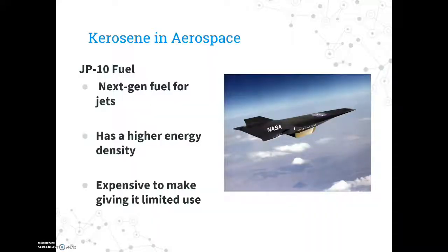The next fuel is JP-10. JP-10 is the next generation jet fuel that's coming into the military. It boasts a higher energy density with a gain of 11% compared to JP-8. Just to compare, JP-10 holds 142,000 BTUs per gallon as opposed to 125,000 BTUs for JP-8.